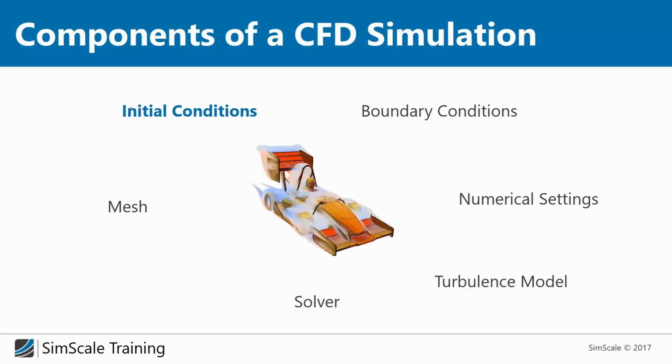As you might remember from our last session, the way CFD simulations are solved, it's iteratively, which means we have a numerical approach, and it's like we are taking our equation, we're calculating it, and then the solution is the input for the next calculation step, which means we need initial conditions. And to make this a little bit more vivid, for example, initial conditions need to be similar enough to the solution we are looking for, but they don't need to be exactly the solution, otherwise we do not need CFD.